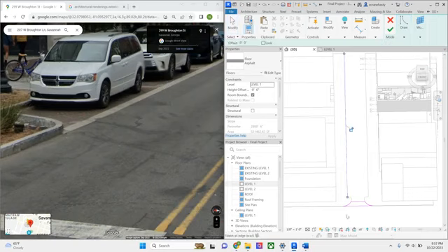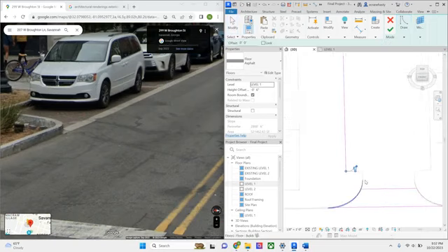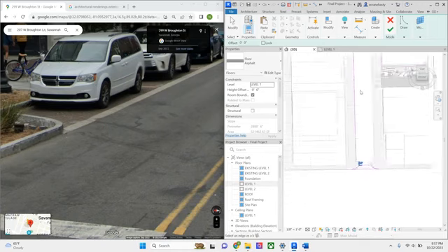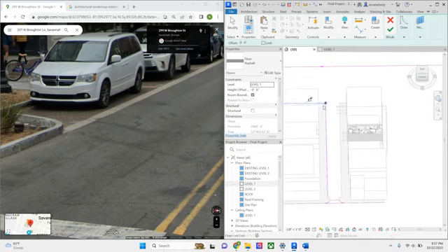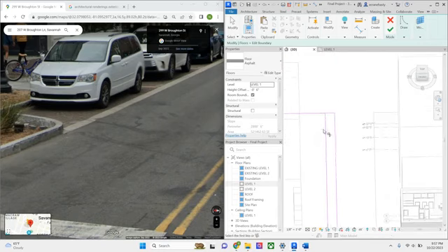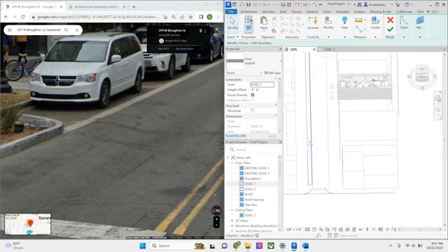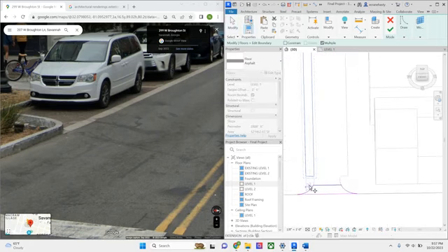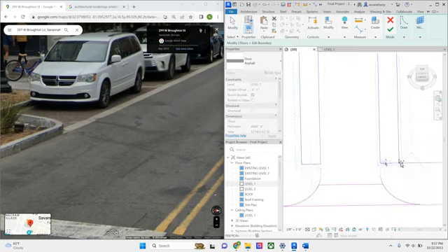So pick lines. I'm going to come over here. I'm probably going to pick that line and pick that line just because I can trim to start closing these boundaries, which is TR. Love trimming. It's one of my favorite tools. I like to copy a lot as well.